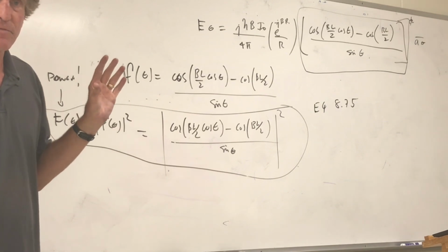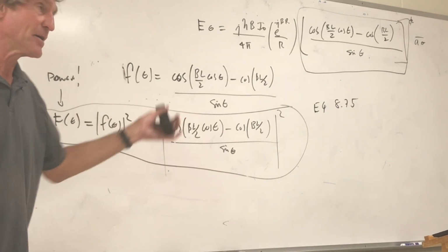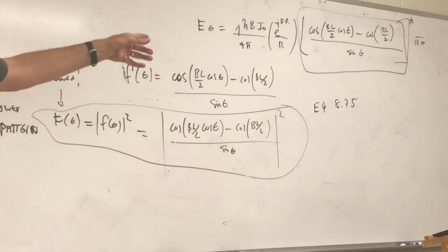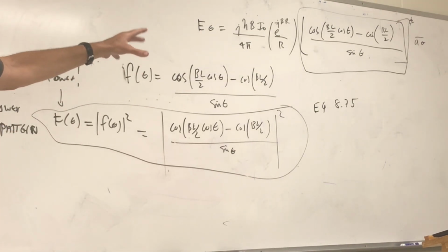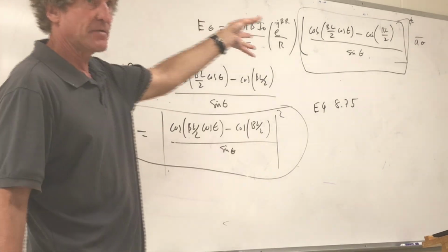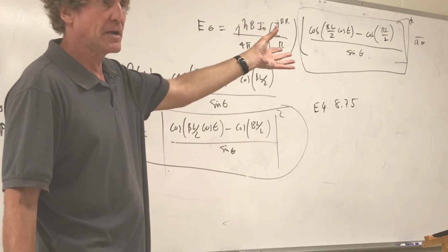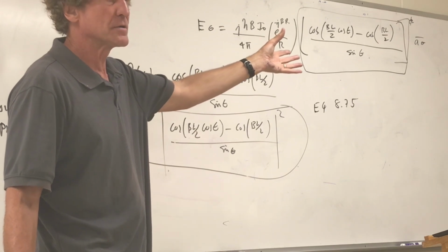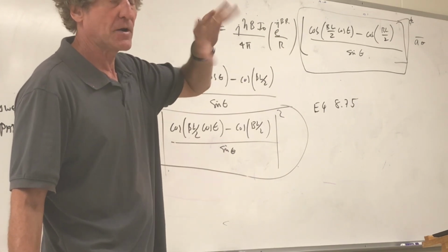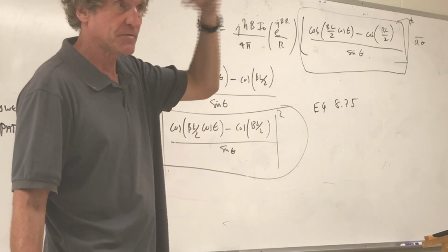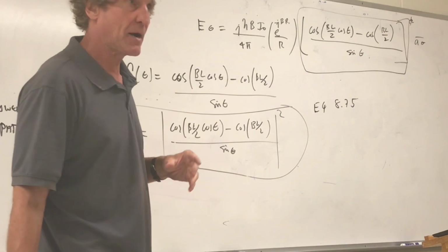Have you heard of a half-wave dipole before? So now I'm going to move to that part. I'm just showing you this. By the way, if that was the electric field, just listen to me now. We can get the radiated power, right? What we do is take 1/2 the magnitude of that squared divided by eta. Now we have the power density, right? Then we integrate that over the spherical surface, with the differential surface of r squared sine theta d theta d phi, and set that equal to the radiated power. You can get it.